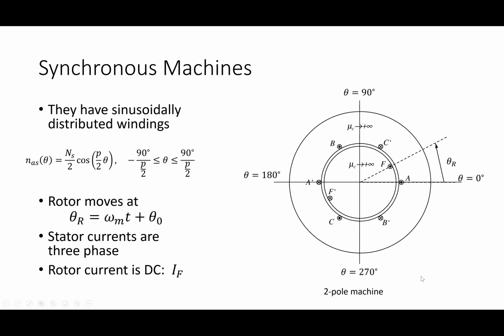So the synchronous machine, generally used as a synchronous generator. This is the cross-sectional picture that I have used for this. I said this is a two-pole machine. Now, what does it mean to say that it has two poles? The direction changes. Yeah, the field basically, as I go around the air gap one time, changes direction once.